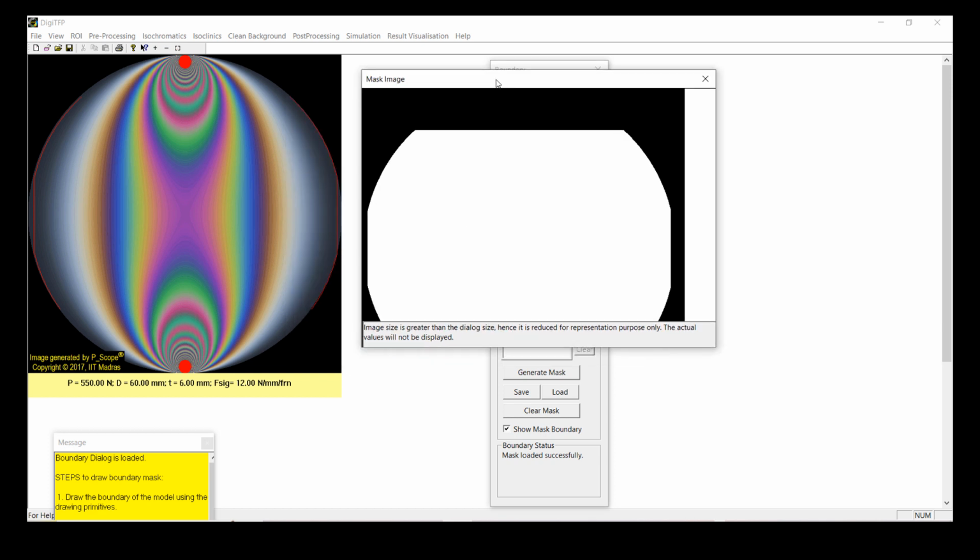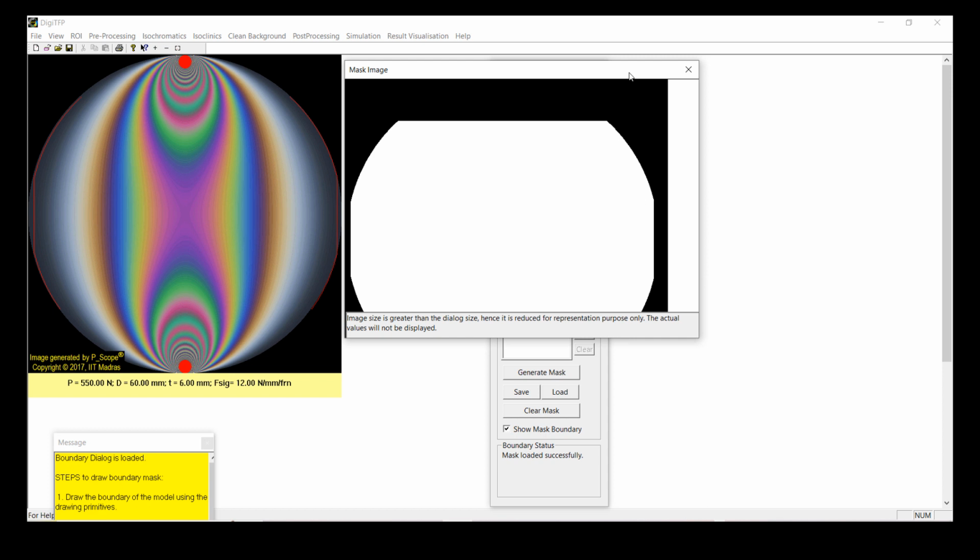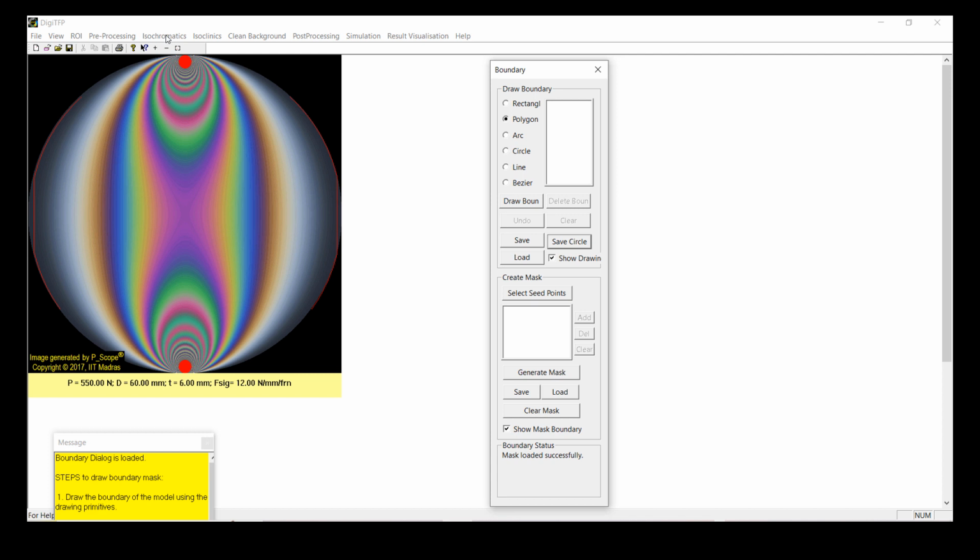There are ways and means to do this analysis for higher fringe gradients also using the same software. But for the purpose of this demonstration, I'll keep it limited to this white area. Now I'll be focusing on isochromatics. This is the color adaptation option where we can do 1 and 2 point color adaptation. This will be useful for calibration tables that have been developed for different material or different tints as opposed to our application specimen. So let me go on to do this fringe ordering.